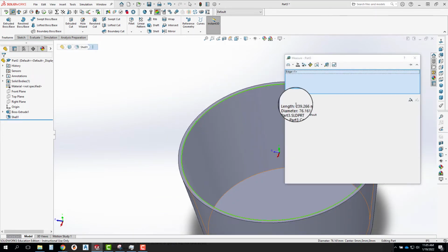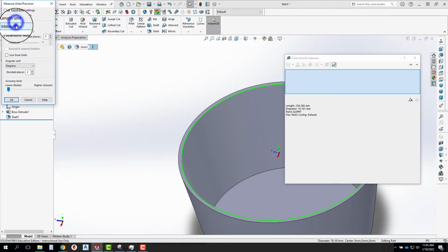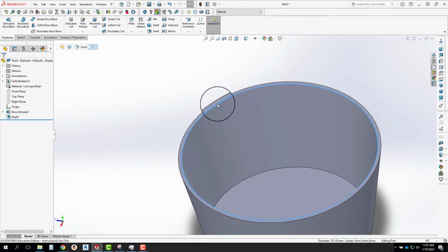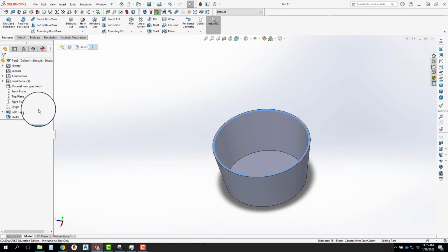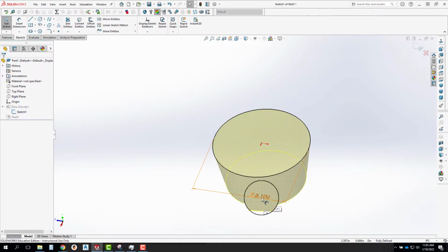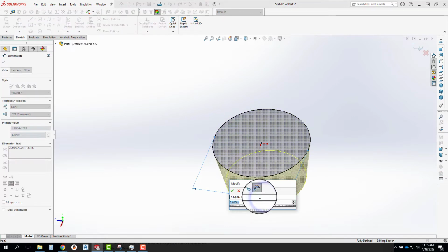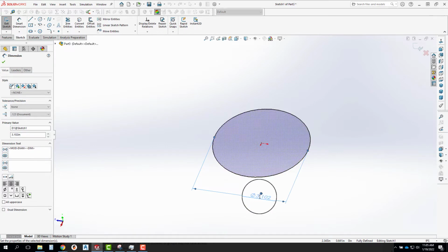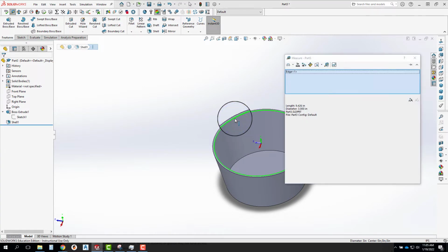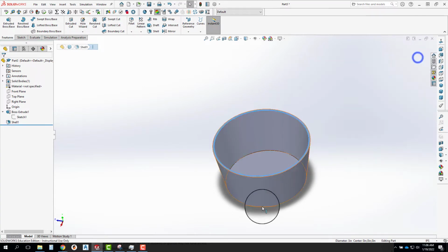The inner dimension, oops, I'm in millimeters. So it's 2 thousandths under. That has to do with the dimension of my taper probably being on a diagonal. So if I really wanted to perfect that, I could go back to my sketch and add 2 thousandths onto my original one. So let's go back, take a look at that sketch, make sure 3.1. So I could do 3.102 and go back and see what that ends up with as a final inner diameter. So yeah, it's 3 thousandths there. Okay, so now I have a cup.